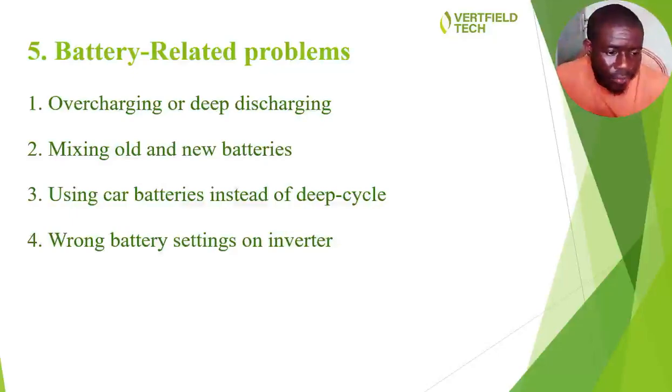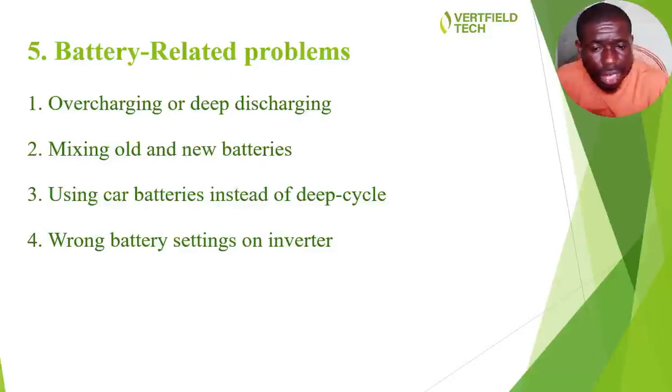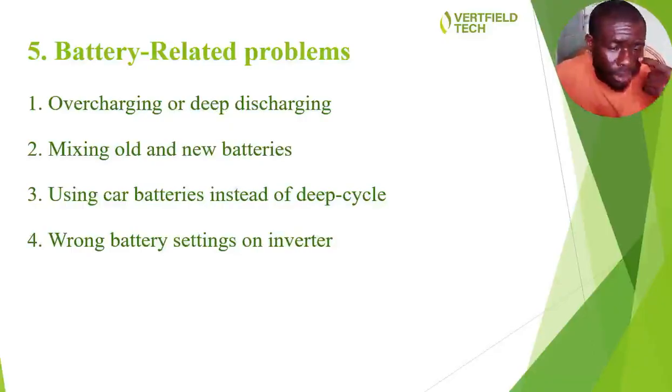And there are a whole lot of technicalities involved in this, but we advise you to enroll fully for our solar installation course, and then we can give you all the information you deserve. Do not use car batteries like I've said earlier. Only deep cycle batteries like your solar batteries are allowed. Your car batteries are just for starting your cars and not for discharging.